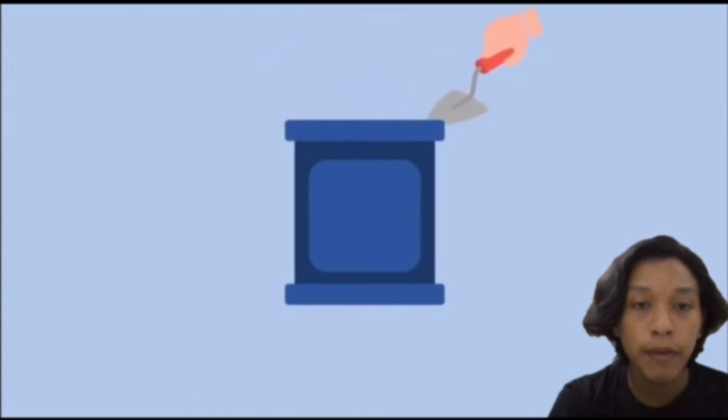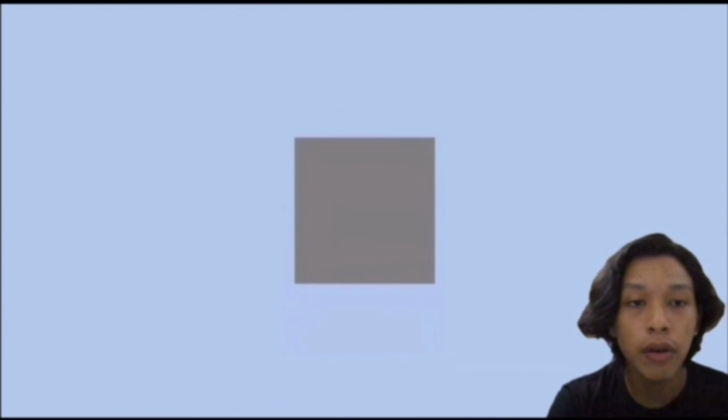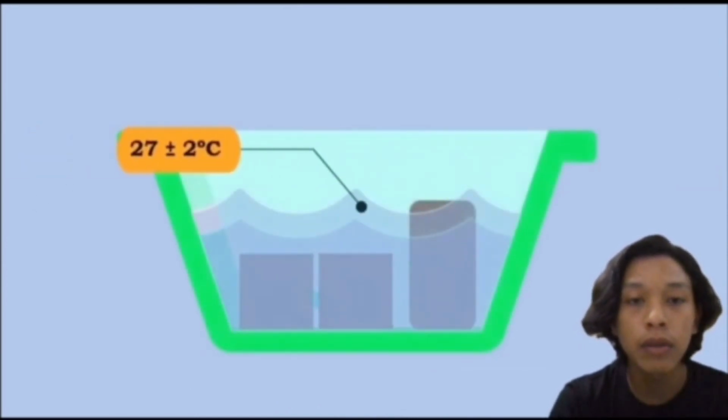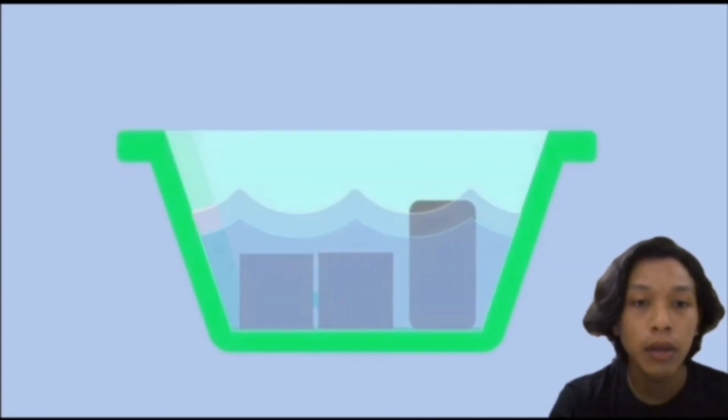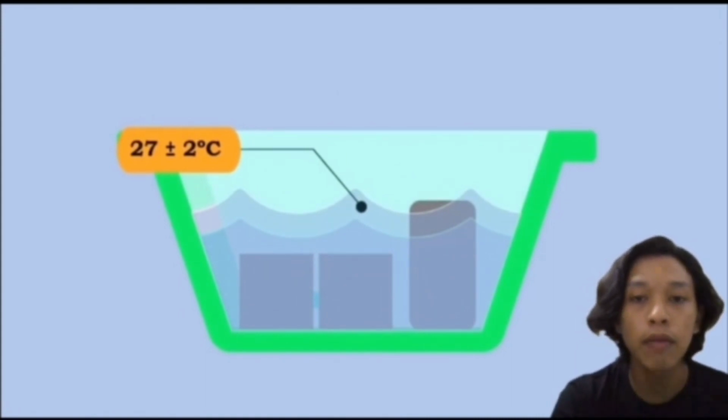After that, finish the surface using a trowel and mark the cubes by scoring on the top, just before the concrete sets, for future identification. Then, leave the concrete in the mold for 24 hours under damp sacking. After 24 hours, strip the concrete cube, weigh the dry cube, and place all the cubes into the curing tank for 7 days.